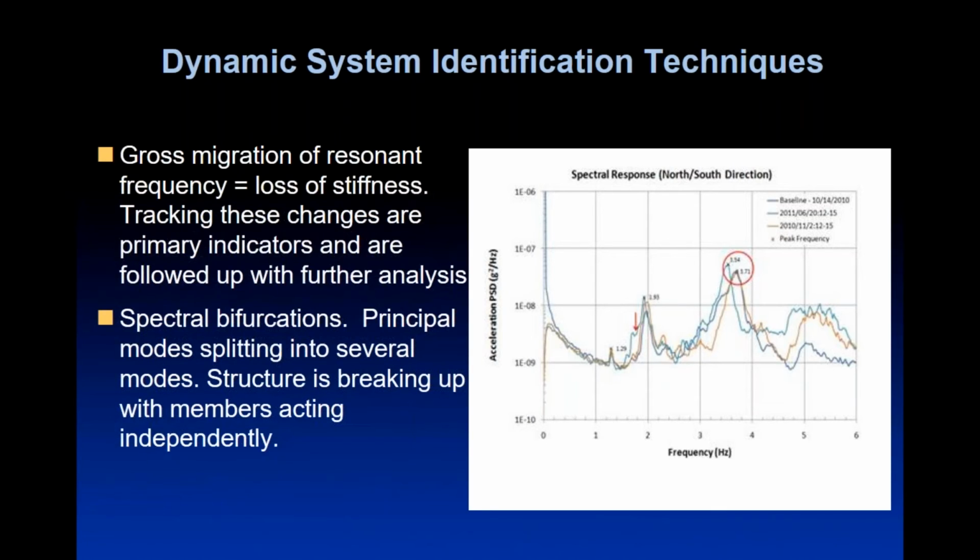And we're very particular about how we do that sort of thing. So we've got differential influences from different places. This is a real response off a building on 2nd Avenue. We have the blue line as a baseline, and then spectra taken at different times, plotted on the same diagram. For the first, the fundamental mode of vibration, we've actually got a splitting up of the peak, a bifurcation occurring there.